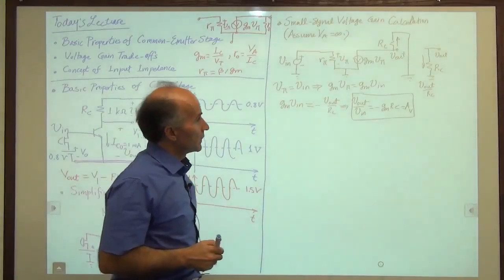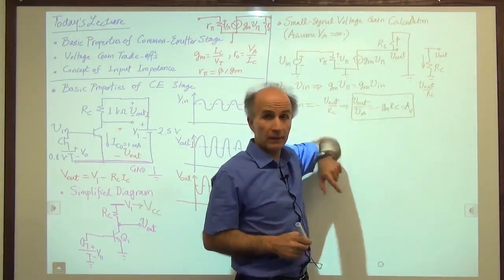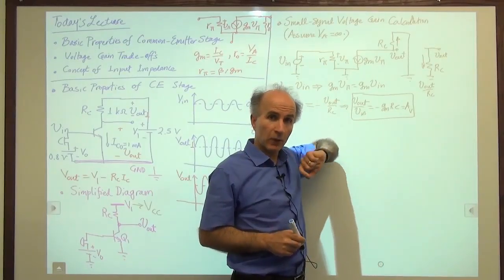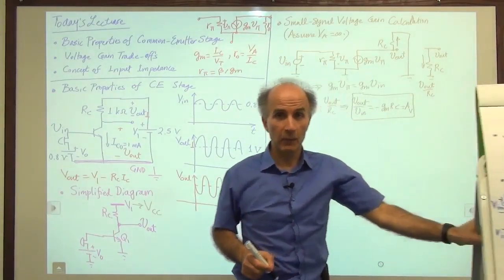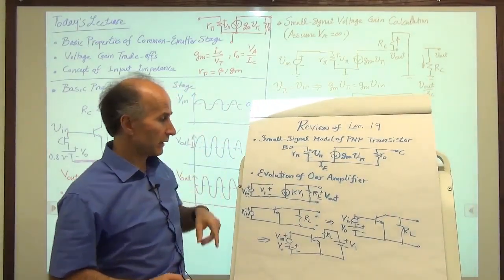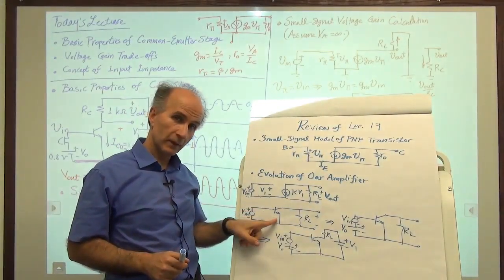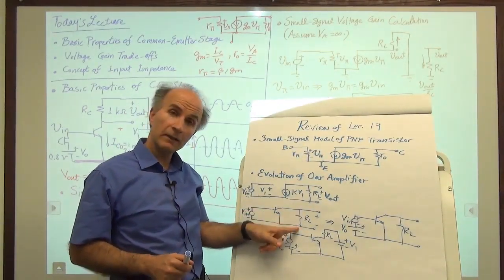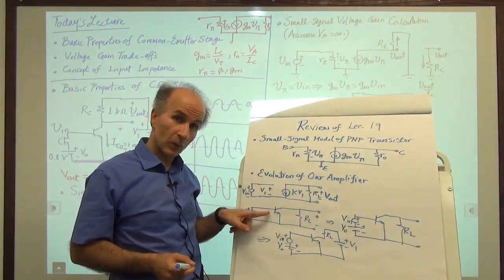Okay, so gm is the transconductance of the device. And now we realize why that very first circuit that we built using the bipolar transistor failed. This circuit here, remember, we connected our microphone directly to it, and we were hoping to have gain. Well, because we had no bias, no collector current, gm was 0.